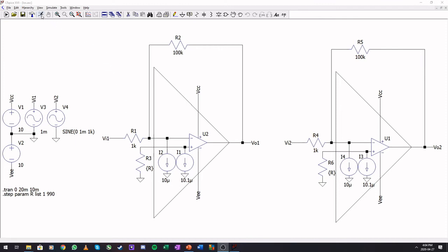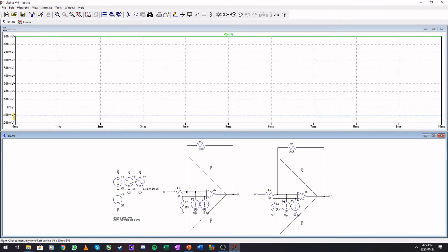They are roughly equivalent. So if you run this simulation, and let's click on the first one, the blue graph here is with our countermeasures added, and this green one up here is without. If we insert 1 millivolt DC, we would expect this to have a minus 100 millivolts out. With the countermeasures employed, you can see that this is roughly minus 100. And in our calculations, we have a 1 volt offset here. So 1 volt minus 100 milli would be 900 millivolts.